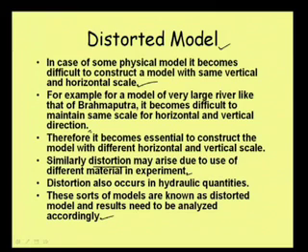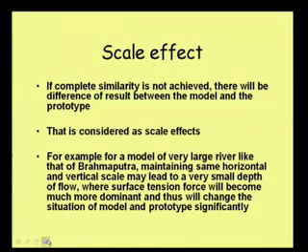Once we are getting the result, if we know that there is distortion in the model, then the result will have to be analyzed accordingly. Then we talk about scale effect. Almost these two are related. If complete similarity is not achieved, there will be a difference in result between the model and the prototype, because we are not able to have complete similarity all the time.